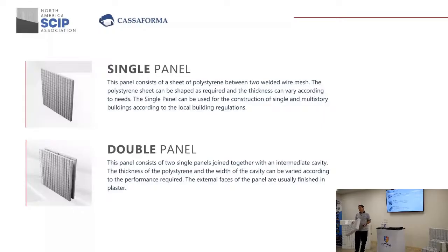I mean, to do some numbers, you will see that it is okay up to 16, 17 at most, depending on the live loads that you have. Okay? So basically, when you go over that, you have to go with this other type of panel that we are seeing here that has some pockets on it. Okay? So why so? Because you have to make it more rigid. Okay, you have to make it more rigid.